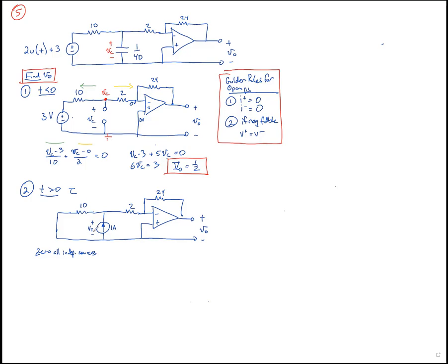And we're scared because it's an op-amp. And that does look scary. And the only thing we know is that there's no current that goes in. And we know that this is 0 volts since it's connected to ground. And we know that if that's 0 volts, this also has to be 0 volts. And we said that there's something magical about doing KCLs.